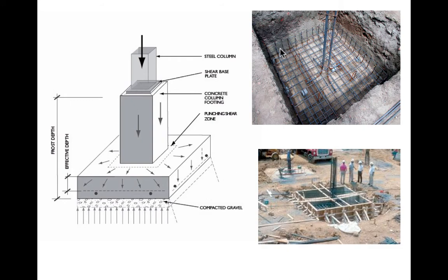And here you see under construction, this is the reinforcing cage for the spread footing. We have reinforcement usually in the concrete column to keep it from spalling or to handle any local bending. And you see that those rebar reinforcing bars in the column are turned out into the spread footing, which helps to handle the shear. And here again, this is the reinforcement that will go in the column, and you can see a little bit of the reinforcing cage in the spread footing down there.